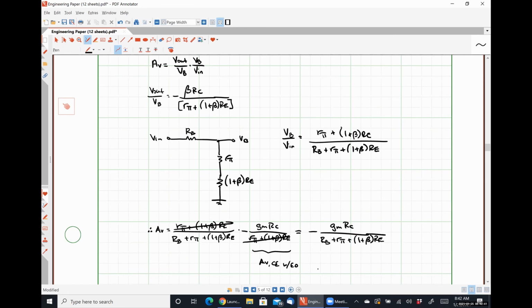So it's lowering the voltage gain overall from our degenerated state, but the effects of this are not nearly as large as the degeneration itself, because that resistor value was multiplied by a factor of 1 plus beta, right? So we can get a large resistance there.